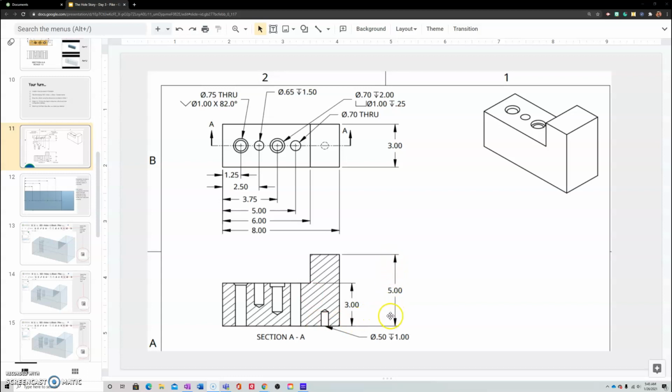So for example, the overall height of this little outcropping is going to be 5 inches. The height to the plateau portion is going to be 3 inches. Depth will be 3 inches. And the overall length is 8 inches. So that's where we would always start. We're going to do additive modeling, and then we're going to subtract out and place our holes within our part.